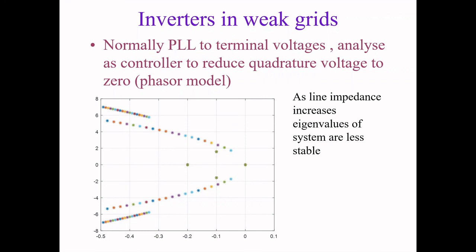And it all comes down primarily to the phase lock loops that are being used. But it's not saying, well, what we need is just better gains on the phase lock loops. I'm saying, actually, no. They're doing a damn good job at the moment, as far as you can. What you need is a better reference to lock to, rather than a better locking process.